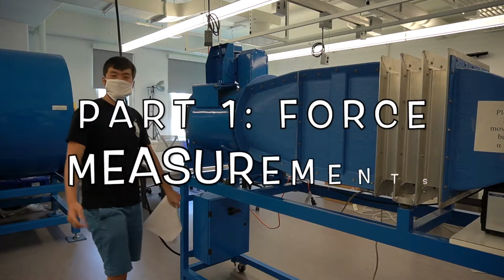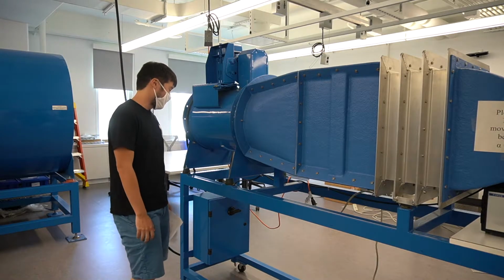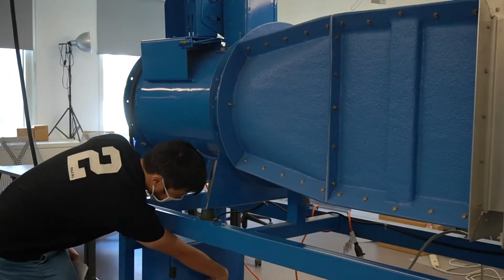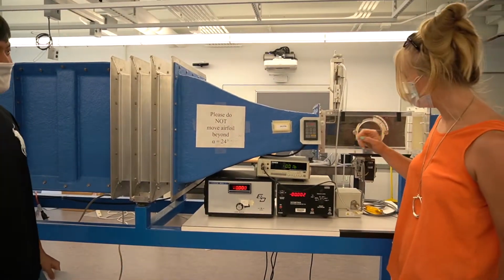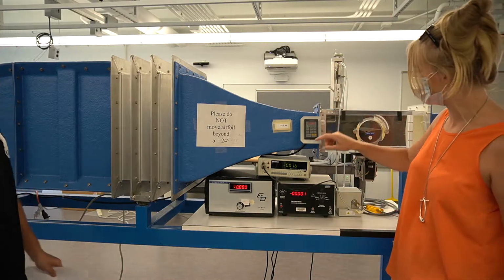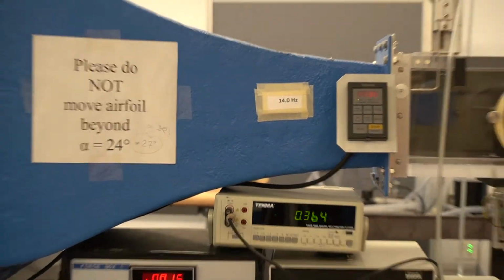Okay, thank you, Skipper, for that wonderful introduction to the first part of the lab. So we're going to start off by turning the wind tunnel on. And so to do so, I'm going to flip this switch right here to on. Okay, and now we're going to come to the control panel, make sure it's set to 14 Hertz, and click run. With a lovely musical introduction.